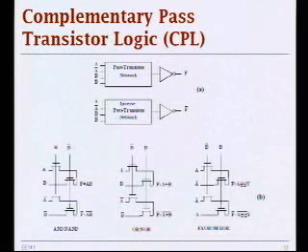The 0 would be good, the 1 would be bad. So if I have redundancy, for example differential circuits, then if F is 0, then F bar would be not good. But at least I have a good output. And if F is a 1, it's not rail to rail, then at least F bar would be a good 0. But we saw this.